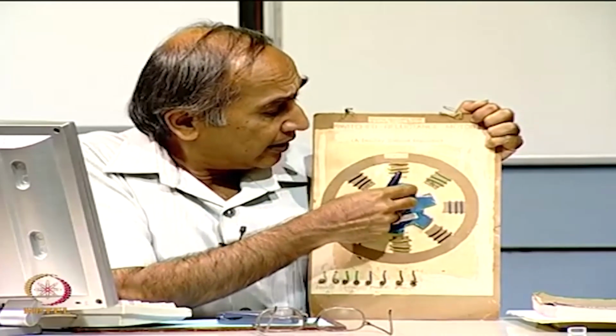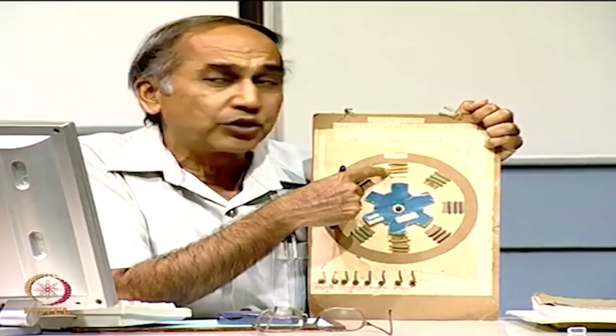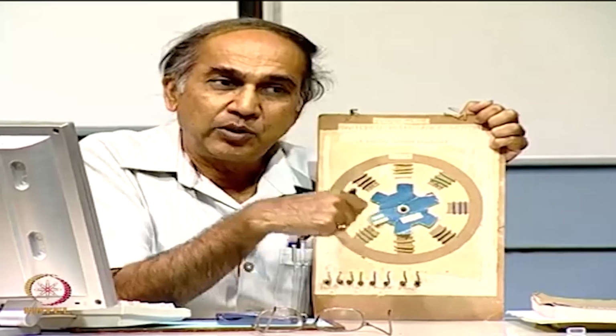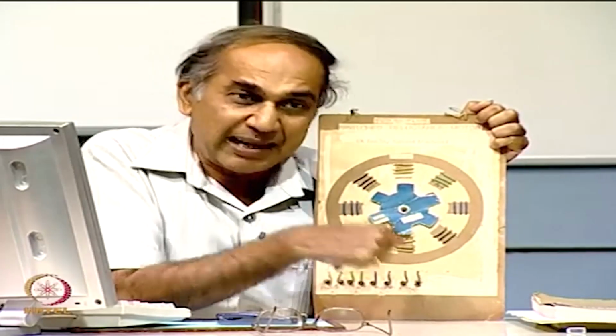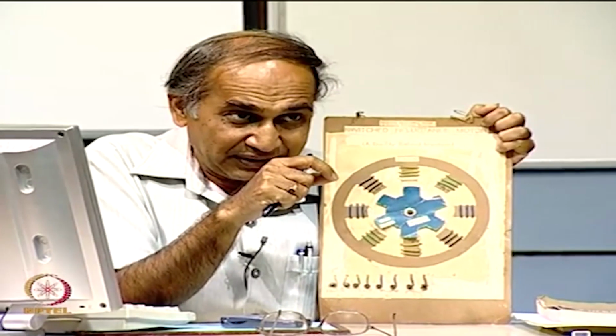Now, another thing. If the rotor is aligned and you pass a current through the stator, say 10 ampere, 20 ampere, 30 ampere, 40 ampere, 100 amperes, will the inductance be the same? No, I have kept the position theta the same. I vary the current. Will the inductance be the same or not? No, it will not be the same because there will be magnetic saturation.